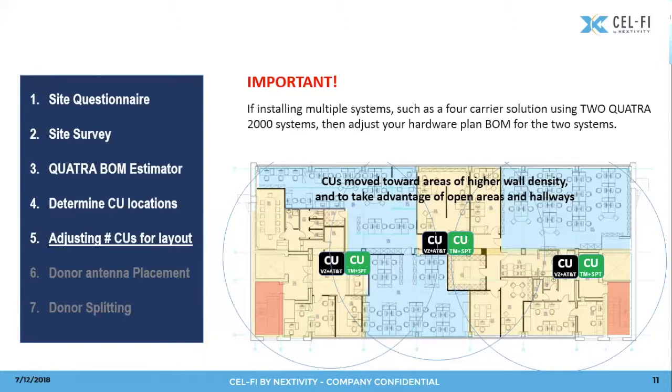And remember, this is a digital system, and Cat5e LAN cabling is dirt cheap. We don't care if that cable's a foot long or 650 feet long. You're going to get the same full output power from it, which means if you're not sure where a coverage unit's going to go, then just leave some extra cable coiled up above the ceiling tiles. And that'll give you some flexibility on moving things later. Can I really go 650 feet on a single Cat5 cable?